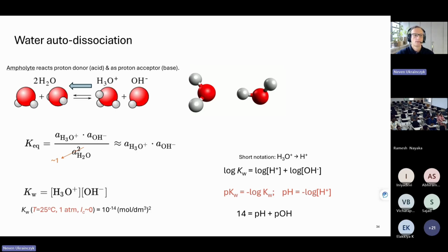So this is why the solubility of Portlandite decreases if you add OH minus, because this multiplication of concentration should stay constant, is always constant at a certain temperature, and it can only stay constant if you precipitate. So you are producing more calcium hydroxide until you get the same concentration which was the initial concentration. So this is why you are basically decreasing the solubility of Portlandite.